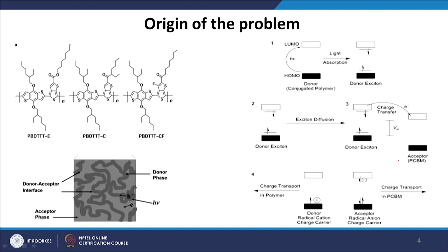Okay. Now, in the context of the organic solar cell, the same thing applies. The first stage is exciton generation. If I have to have a good exciton generation, that means I need to generate more and more charge carriers. So, for that what should I do? We should make materials which can absorb the light over a broad electromagnetic spectrum. That means we need a material with a lower band gap, that is called a low band gap polymer. These are some examples of low band gap polymers which people have synthesized, and you can see their chemical structure like this. These materials are very good at absorbing the light and their absorption coefficient is also very good. That was the first step.